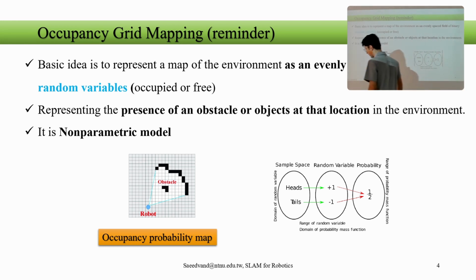If you want to visually see what's happening, we have the probability of a cell being an obstacle or not. I don't know how visible this is here. These are darker colors, these are white, these are black. For the darker colors, we can say we didn't see, we don't know, the robot didn't scan. But this area that is white means that we scanned, and when I'm scanning, there is an obstacle here.